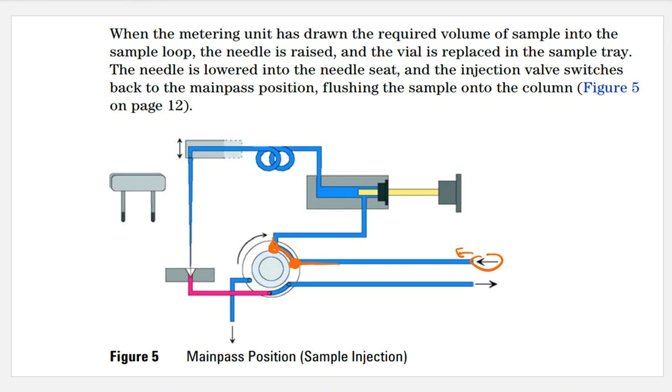So the mobile phase is going to go in. The mobile phase continues through the injection port. The mobile phase ventures up into the analytical head. The mobile phase goes through this tubing line that did have your sample loaded up in it. I don't know how much was in there. It really depends on what you've told the machine to suck back, but there was sample in there.